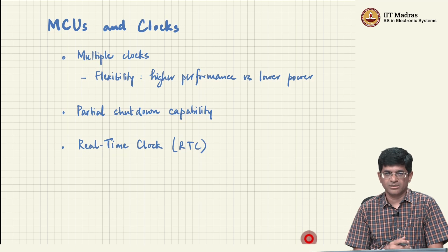So just by having this one alone, for example, you could trigger it to do things like maybe wake up once every few seconds, do some work and then go back into deep sleep. The rest of the microcontroller will just be completely asleep. The real-time clock alone will take care of waking the system up, getting it to do some work, and then finally the system can go back to sleep and wait for the next tick from the real-time clock. So it looks like there are some benefits to be gained from this, and knowing how to control the clocks in a system can play an important part in efficient design of an embedded platform.